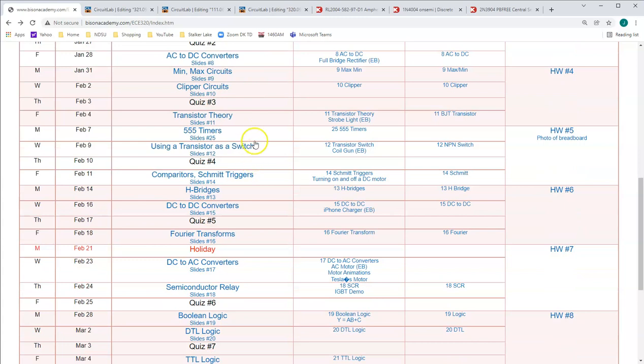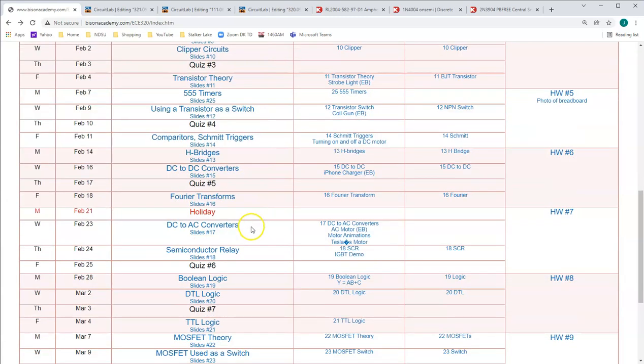If I take three types of silicon, put them together, I get a transistor. With a transistor, I can build a switch, have something wimpy like a 555 timer turn on and off a speaker, turn on and off a motor. I can use an op amp and have the motor or a fan being turned on and off with temperature. I can build an H-bridge, have the motor go forward or backwards. I can convert one DC voltage to another, and I can convert DC to AC.